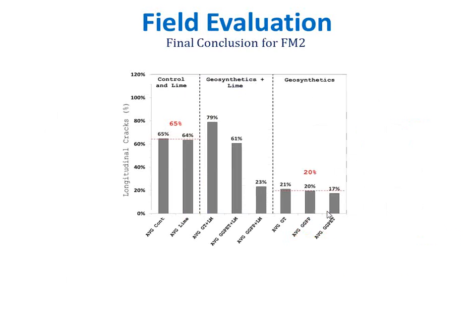The important aspect that I wanted to give you, and this is a different way of looking at the results, this is control and lime. This is geosynthetics on lime, very uneven. So the presence of lime sometimes made reinforcements not work as well. This is geosynthetics, no lime. And this is percentage of longitudinal cracks. Certainly, these outperformed by far the other two.